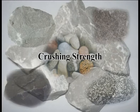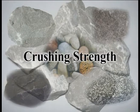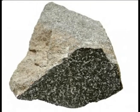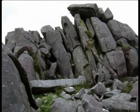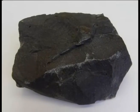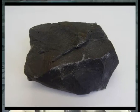The following physical properties are considered to be important for a rock stone as a building material. One important physical property is crushing strength. Crushing strength is also termed as compressive strength of a stone and may be defined as the maximum force expressed per unit area which a stone can withstand. Any force beyond the compressive strength will cause a failure of the stone.